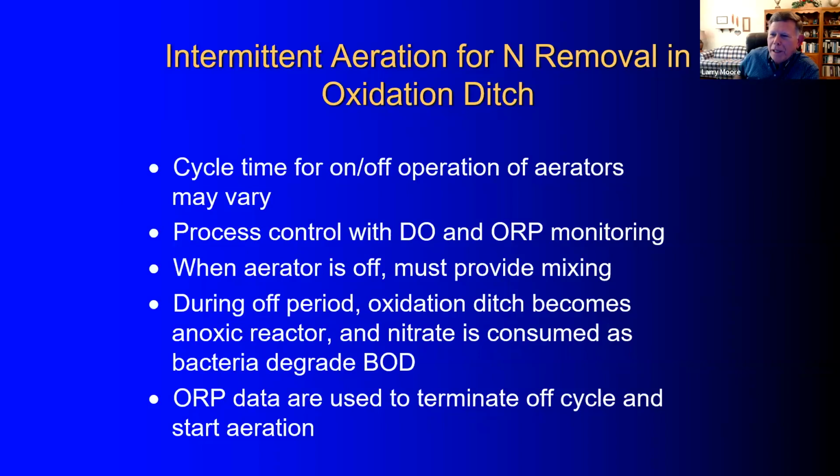What I usually recommend is that you turn your rotors off maybe 3 to 6 hours a day, and by doing that, while the aerators are off, the DO is going to go down to 0 in about 15 or 20 minutes, and we'll have 3, 4, or 5 hours of anoxic metabolism taking place, and we can achieve excellent denitrification even if we're not providing mixing. Even if the biomass settles, which it will, we can still achieve real good denitrification in a ditch by turning our rotors off.